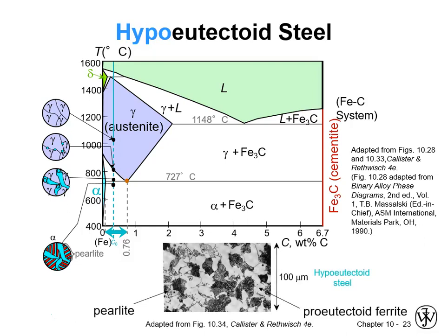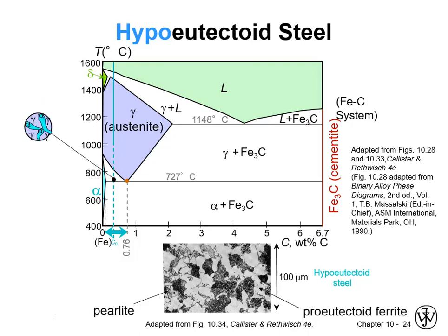And this is what that type of microstructure would look like for real in an optical micrograph, where the large white grains are the proeutectoid ferrite that have grown on the prior austenite grain boundaries and formed their own grains, and then the lamellar pearlite, or eutectoid phases microconstituent, corresponding to all of the remaining austenite that was there. So this is a reasonably low carbon steel, just judging from the ratio of alpha ferrite and pearlite present.